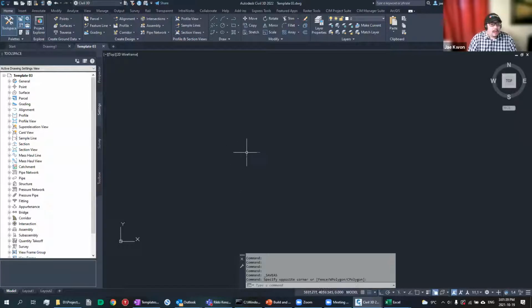Okay, so now that I have some layers to work with in this drawing, that lets me set up a bunch of different things. For example, I can set some general Civil 3D styles. So now that I have some text styles and layers set up, I'll just go into settings and right click on the drawing title and select edit label style defaults.